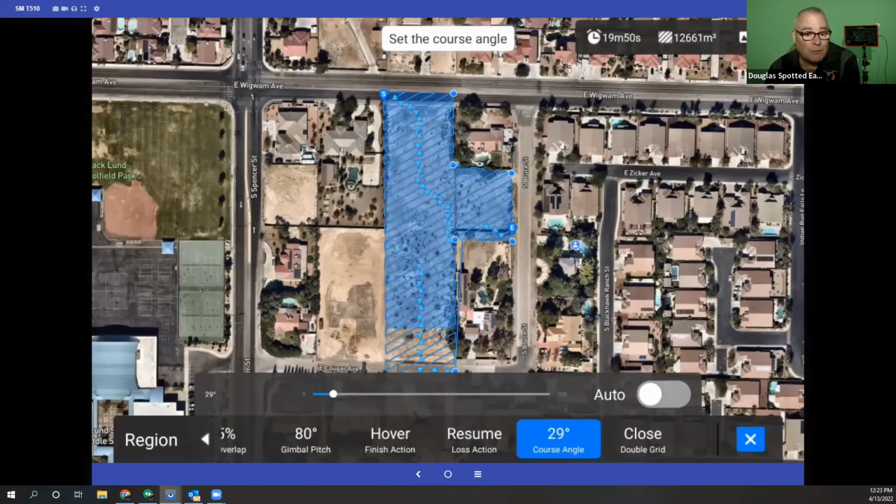If there's a big delta between constant wind speed and gust speed, chances of having a very successful mission are pretty slim. So if we're seeing constant winds of say 15, 18 miles per hour, but we're seeing gusts of 30 miles per hour, that's probably not going to work very well for you and your aircraft. But if we're seeing constant winds at 25 miles per hour, you're good to go. If those gusts are only 28 to 30 knots, it's not a big deal at that point.